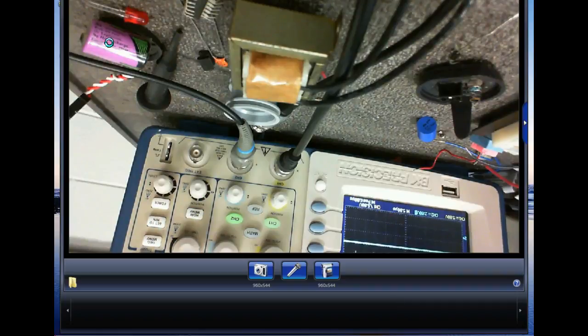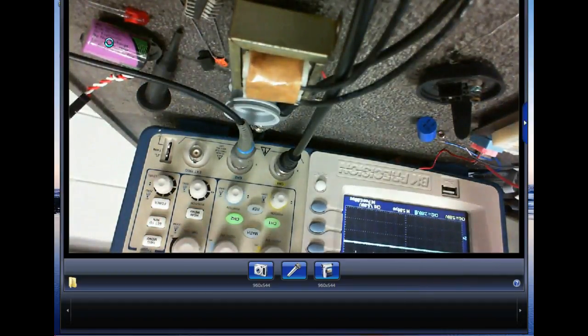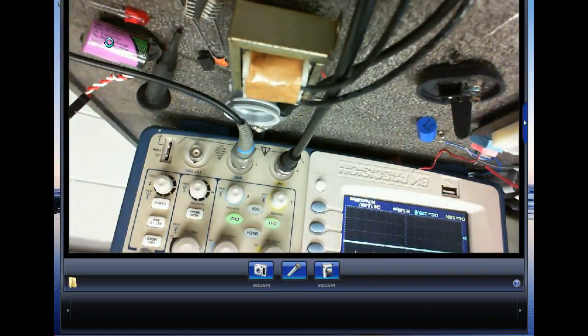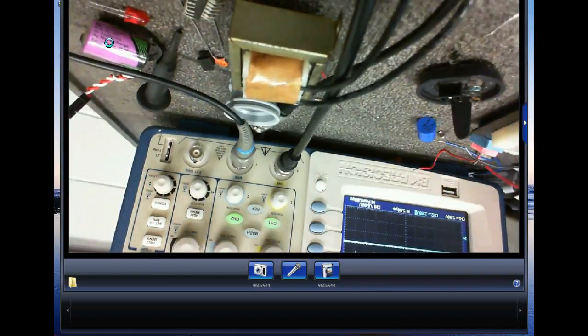And watch what I'm doing. I'm not going to change the frequency. What I'm going to do is change what we call the duty cycle. The duty cycle is the width of the pulse. So notice when I make the pulse, I'm not going to change the frequency. If you look at the two negative edges right here, you'll see them now removed. But I'm going to change the width of the pulse, so we call it pulse width modulation.